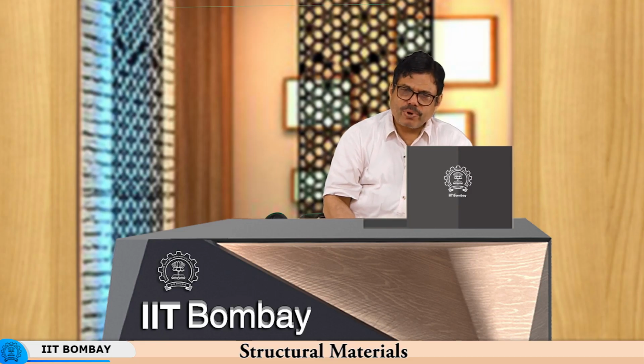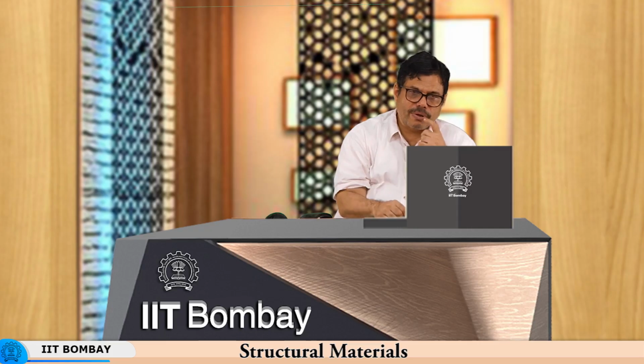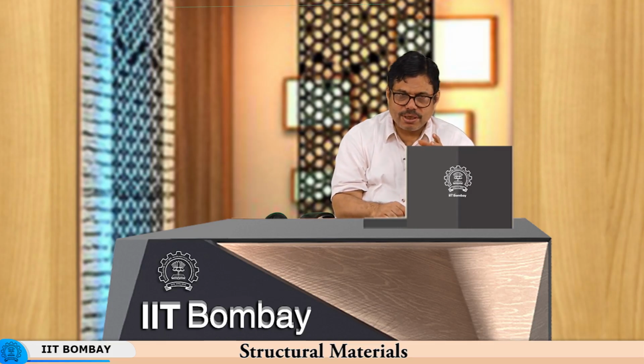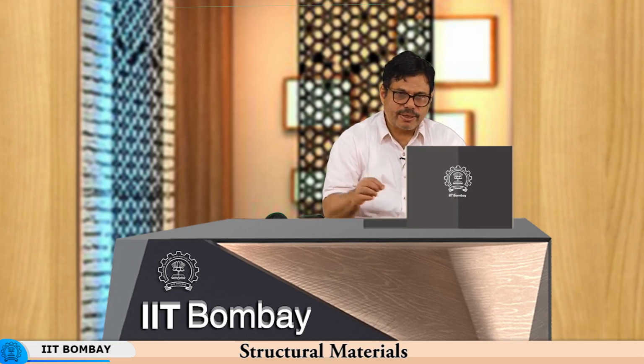Now, in this whole process of volume change, the dimensions also get altered, because when the volume change takes place, naturally the cavities become smaller. For example, you have machined a die or something with a certain hole diameter. Now, after the heat treatment, the hole diameter will tend to become smaller than what it should be, because the volume expansion due to martensitic transformation will make it smaller.